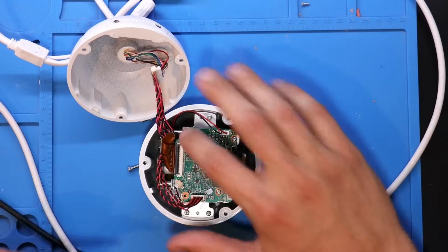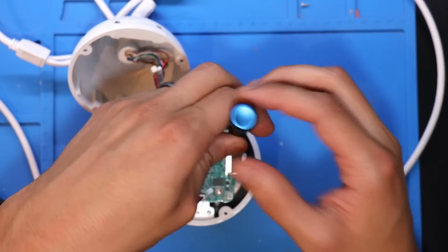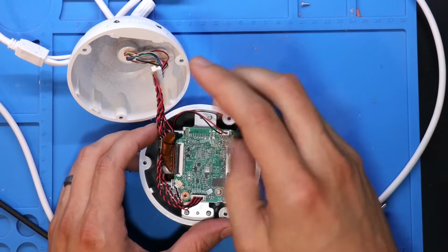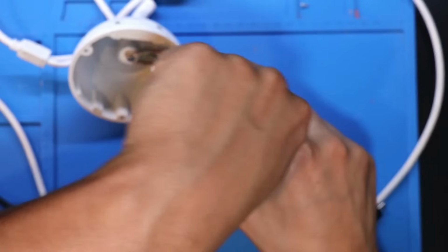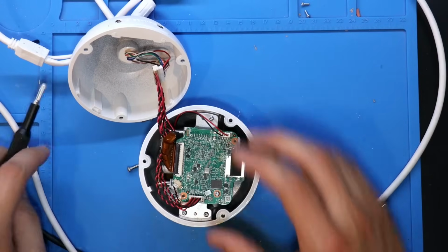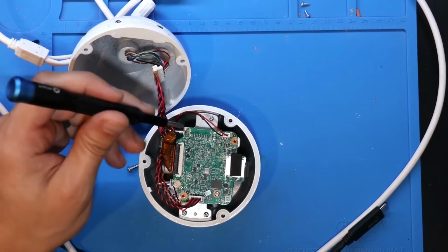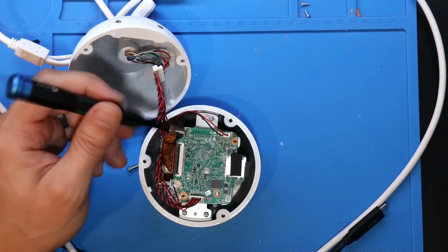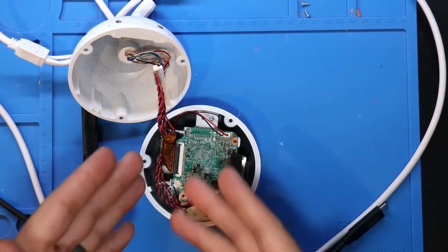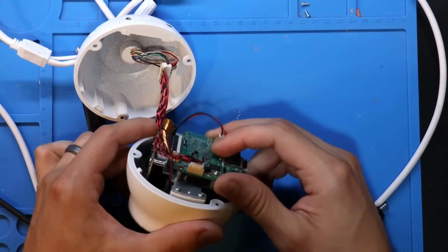We are going to be interacting with that interface because, as we talked about in our slides, one of the interfaces we always look for, especially on a Linux-based device, which, spoiler alert, is what this is, is UART. UART usually shows up as a set of four pins, which is why my eyes just directly go to that spot on the board.